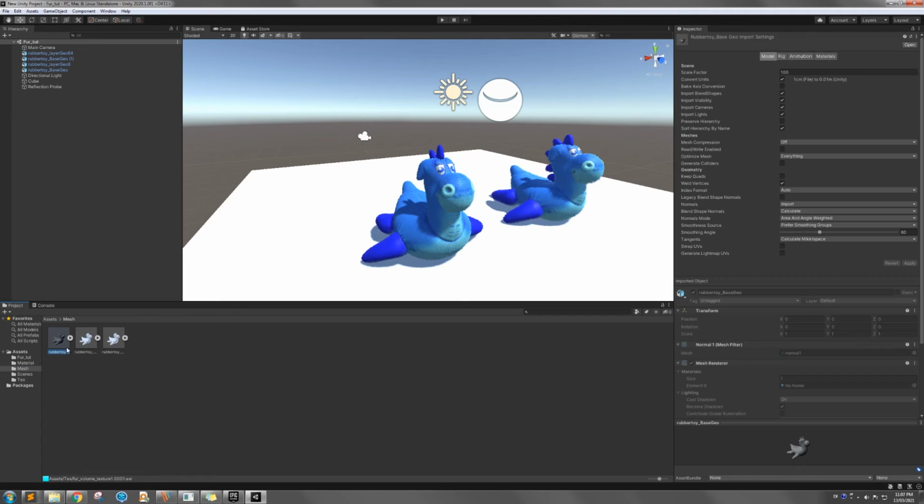So for the mesh, when I import it, there is a base mesh geometry, and also two different densities imported. One is an 8 shell layer, another is a high density one for the long fur, 64 layers. When you import it, you need to make sure you import the vertex color, and then import the volume texture here.